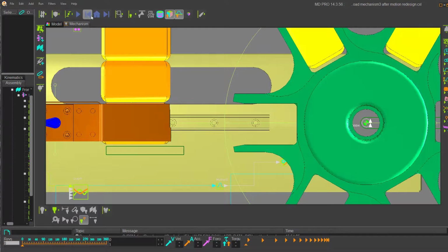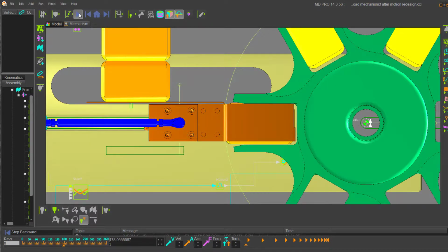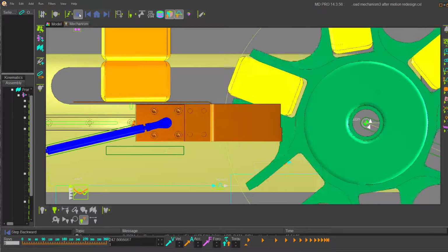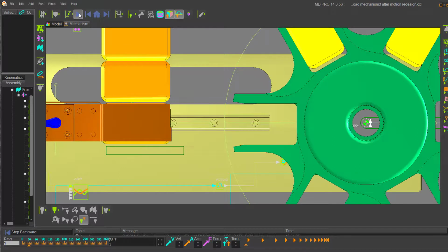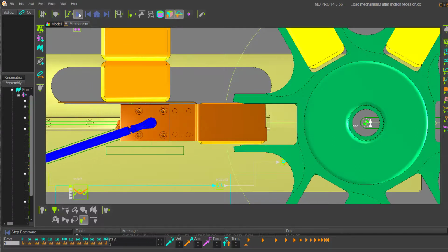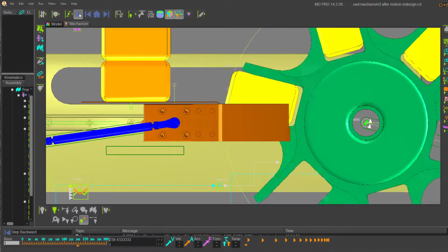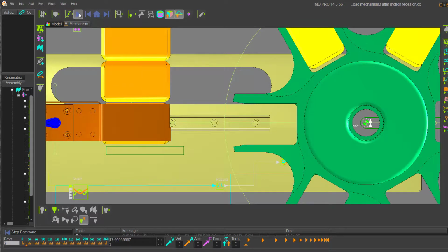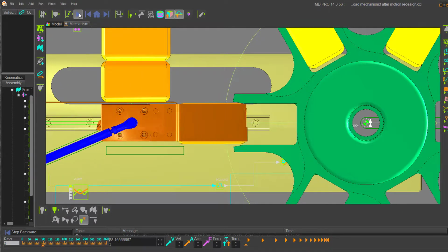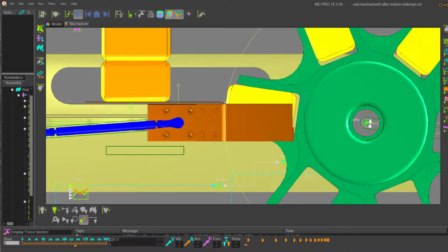Stop. Okay, I've now advanced the turret motion to 15 degrees, and I think this is pretty good now. So it clears, yeah, that clears, everything clears. Oh, maybe it just catches the corner. We might have to put a little chamfer on the end of the top of the pocket, but I think that's pretty good. Yeah, the ingot clears, the tang, yeah, it's a bit close. If there's some vibrations, you can imagine that hitting, so it's a bit tight. Nevertheless, I think for the purposes of this exercise, that's complete.